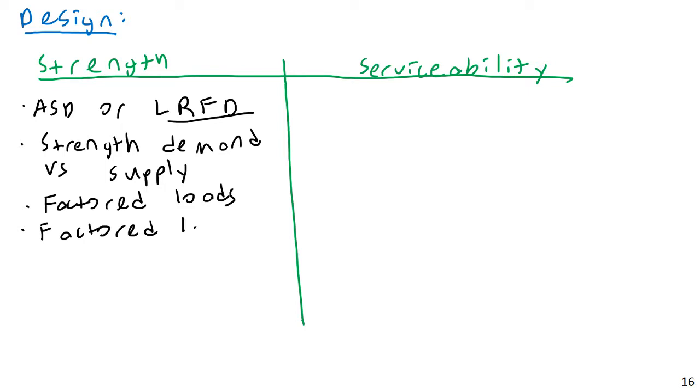So when we first calculate a load, for example, dead weight, we will say, okay, what is our best estimate of the dead load for the structure? Then we'll add a multiplier, 1.2, 1.4, whatever that multiplier is, and we will increase that dead load. Same thing with live load. We'll do our best using the codes and relevant standards to estimate what the live load on the structure is actually going to be, and then we add some on top of that as a margin of safety.